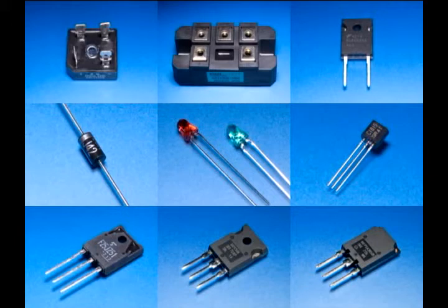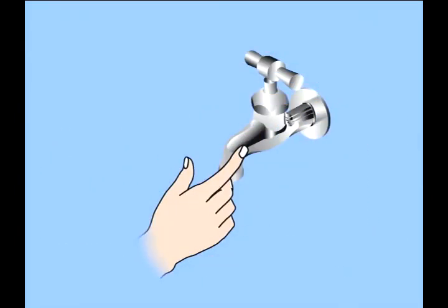Touching a semiconductor device in this state can cause the device to break down, a situation that can go unnoticed, since visibly it does not appear to have changed. To prevent electrostatic destruction, it is necessary to remove static electricity from the body prior to handling a semiconductor device or electronic circuit board. It is easy to rid yourself of static electricity.